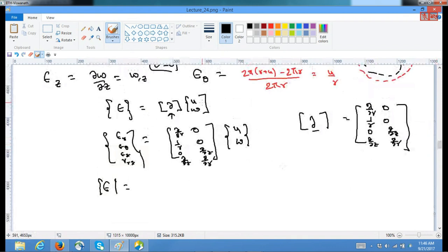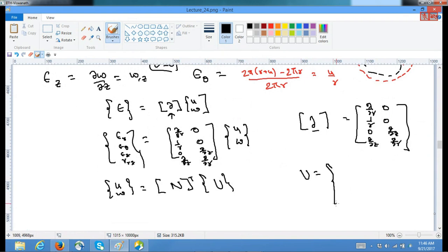So that is the definition of it. So then what you will do is, for this uv has to be used as an operator notation, so as an approximation. So we know that our u and w, each one has to be based on the shape functions times our capital U. Our capital U in this case can be defined as u1, w1 at node 1, u at node 2, w at the node 2, u at node 3, w at node 3, u at node 4, w at the node 4.